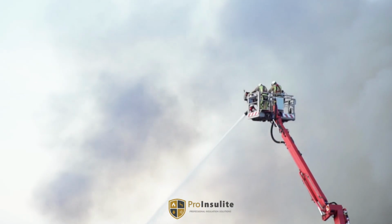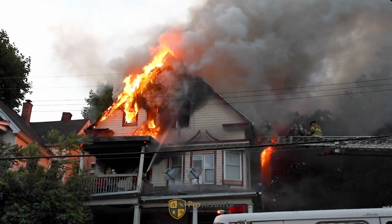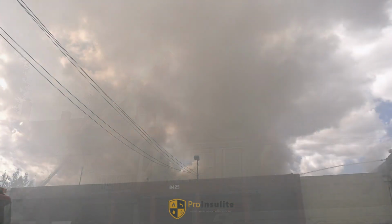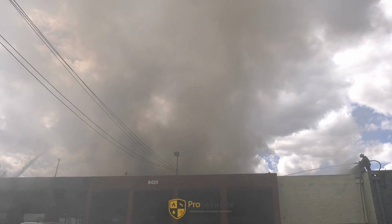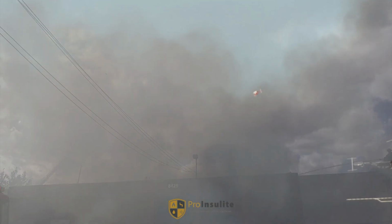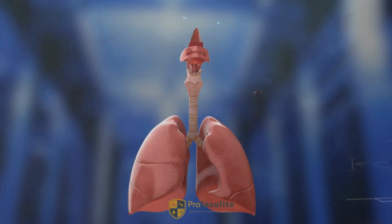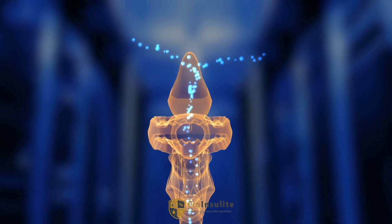Smoke is one of the most critical hazards in fire, particularly in enclosed spaces. It originates from incomplete combustion, where insufficient oxygen prevents full fuel oxidation. Instead of producing only carbon dioxide and water, the fire generates a complex mixture of unburned particles, droplets, heat, and toxic gases, collectively visible as smoke. In real fire scenarios, smoke is the primary threat to life. Most fatalities occur due to smoke inhalation, toxic gas exposure, and oxygen depletion rather than direct flame contact.